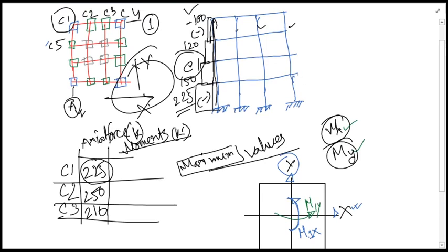So by this time you might have drawn the diagrams for all of the combinations. If you have drawn the bending moment diagrams, you need to sort out the bending moment diagram combination and the maximum values of Mx and My. So from which diagram you will be getting the bending moment of x, and which one will give you that My, that is our main concern here.